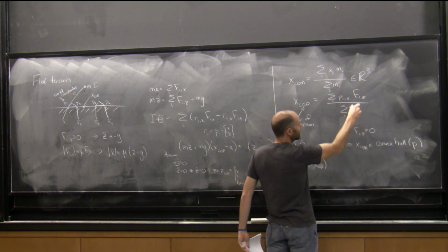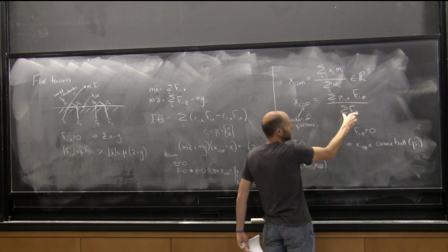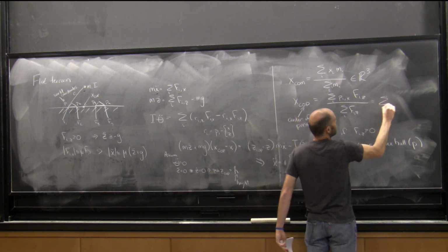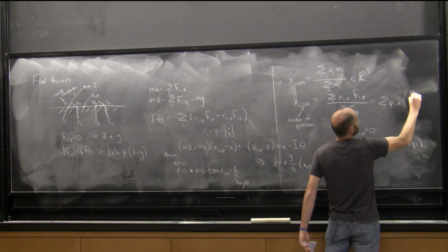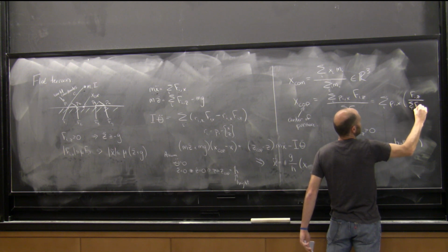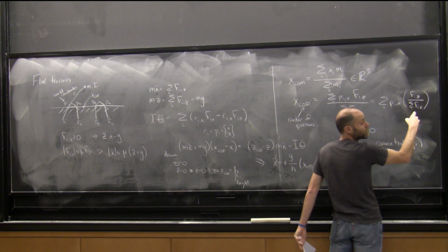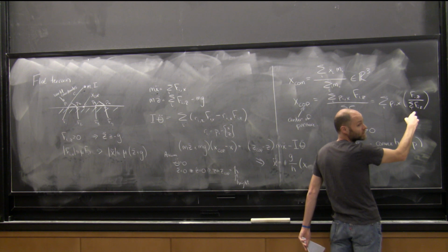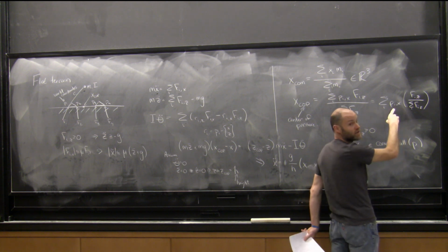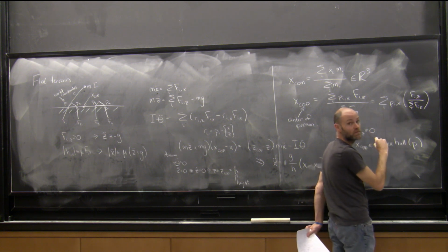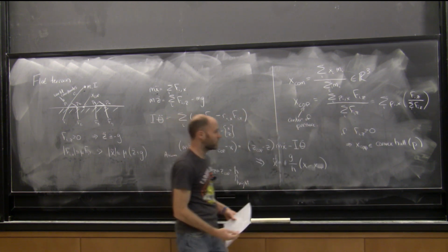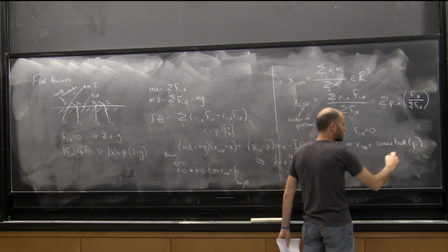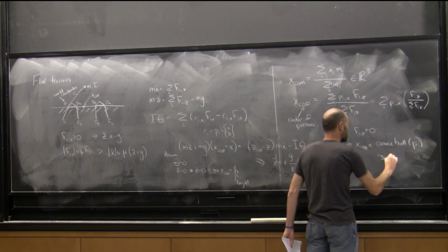Well, if these are always positive, then if I write this as the sum over i of p_i,x times f_i,z, over the sum over i of f_i,z, this is a number that's between 0 and 1. It's an affine combination of these things. It's going to be inside the convex hull, right? So of course your center of pressure stays inside your convex hull. This convex hull, if you're a walking person, is called the support polygon.